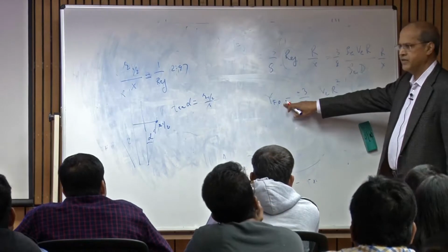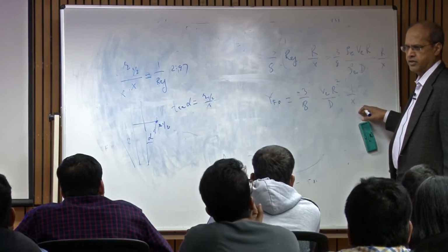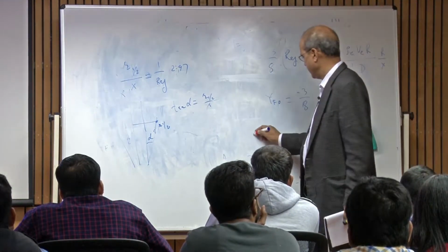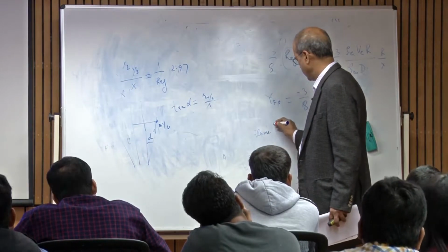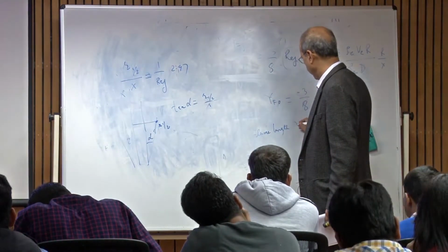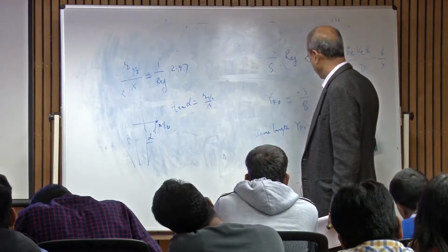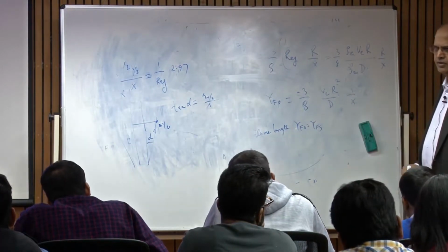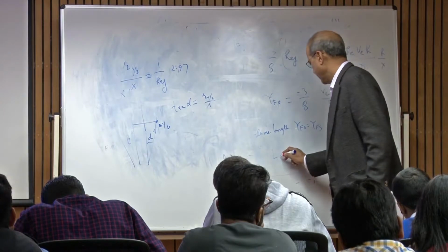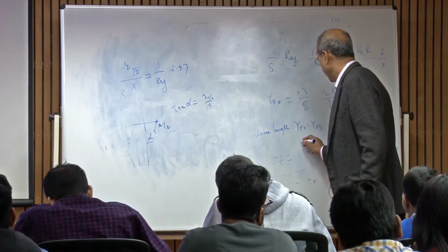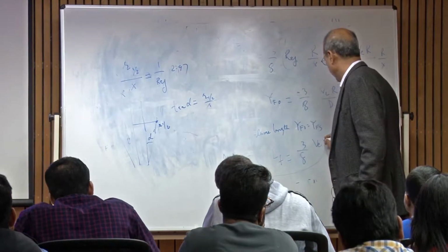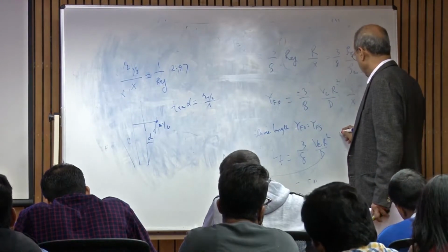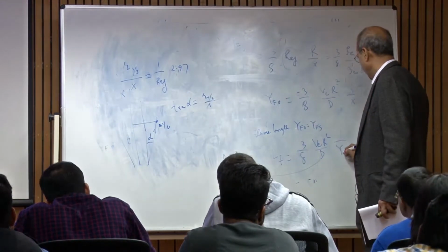So now you see the YF at the center line is decreasing as 1 over x. So to find the flame length, YFO should be equal to YFS, and then the x will give us the flame length. So if you do that, then the flame length will be 3/8 V r square over d, divided by YFS.